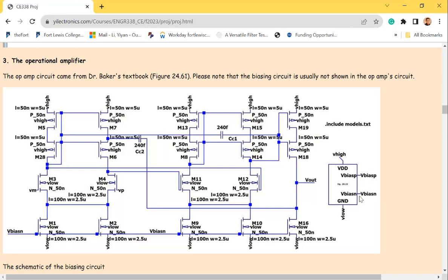See, the biasing circuit is providing a biasing N, balancing P for this. VGS equals... so IDS equals (VGS minus VTHN) squared times blah, blah, that thing, right? So you need a gate voltage to provide an ID for all the circuits. That's why you need a biasing circuit. But you need to turn it on. You know what I mean? You need to turn it on. So this is the voltage to turn it on.